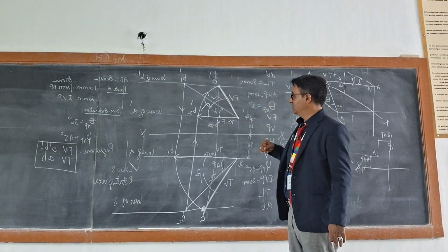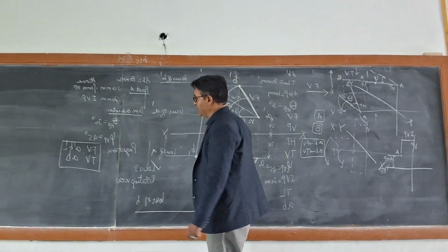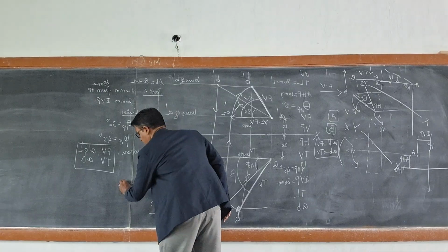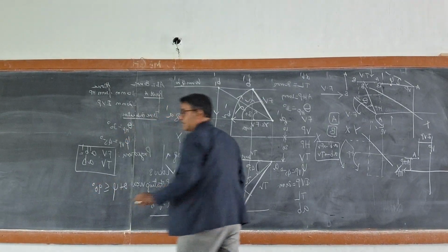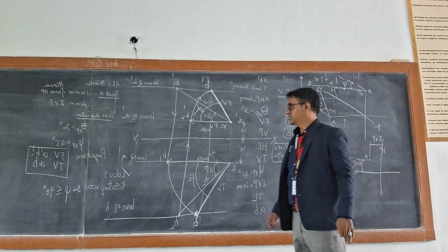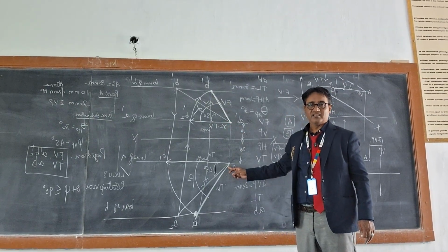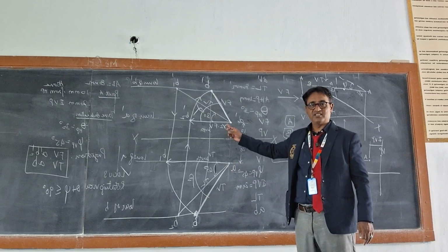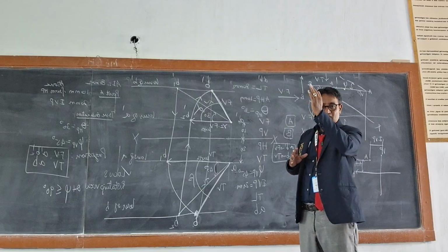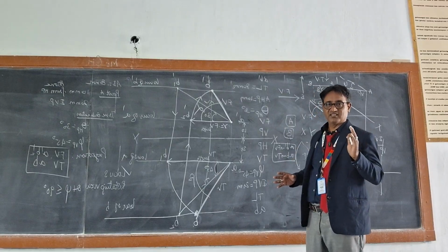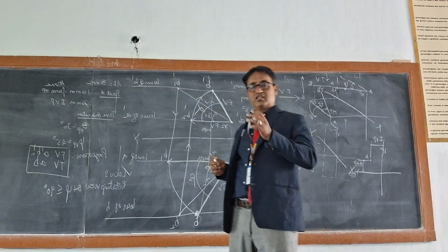And the other one you can understand is when you add the true inclinations, theta plus psi, it will be less than 90 degrees. Suppose it is more than 90 degrees, what will happen is the end points A dash, B dash, A, B will not be in line with each other, meaning the projectors will not be perpendicular to xy. So that is one way of checking.